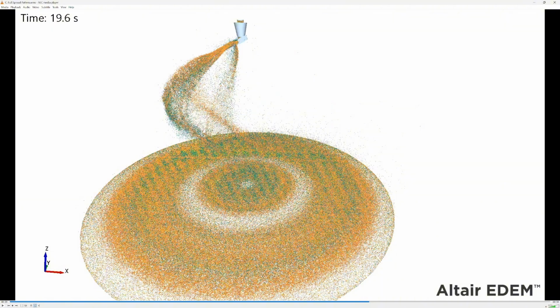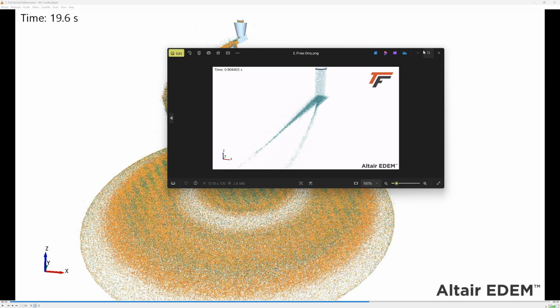We then took that data back and we did some airflow modeling, and we did some calculations to see if the fines were concentrated in this circle or in this circle or in the whole bin, what would the clean corn factor be? And we actually were able mathematically to show the same results. So we feel like we have some really good test data there, and we've seen that data show up in other university studies as well. We did a whole white paper on this subject, and if you're interested in that, reach out and we'll get you a copy. I'm going to show you now a photo.